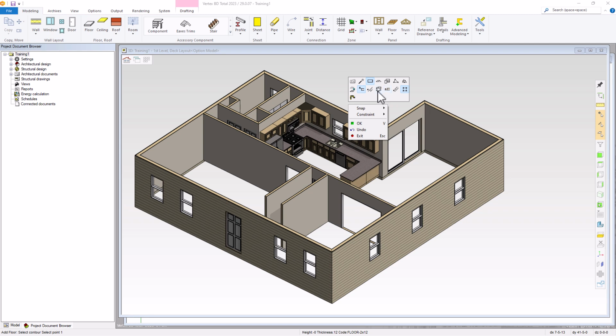And then you can reset your default height if you modified the height. But primarily you want to make sure that you're using either add using points or add using walls. For 3D, add using walls works best. If you are in the 2D view, you can use either one. Add using points is useful if you have a structure that doesn't have continuous linked walls. It's common to have beams between walls that break up the continuous link, and add using walls will not work for those conditions. Let's go ahead and select add using walls.